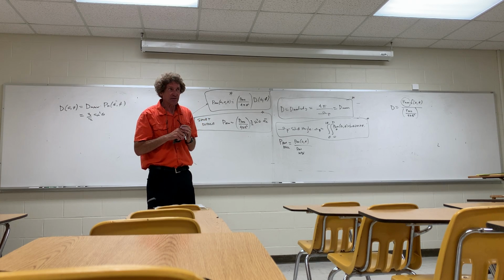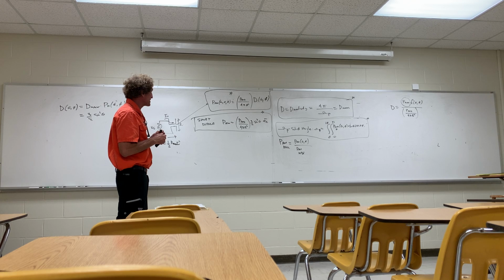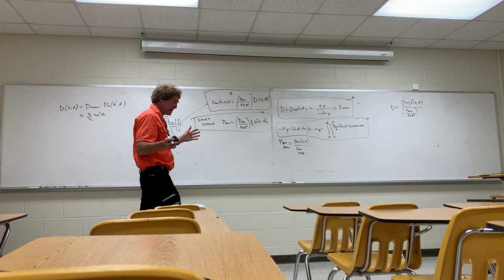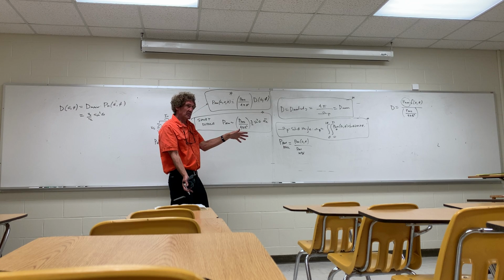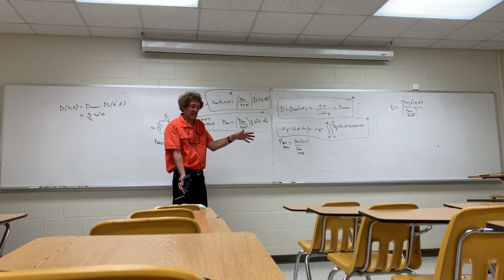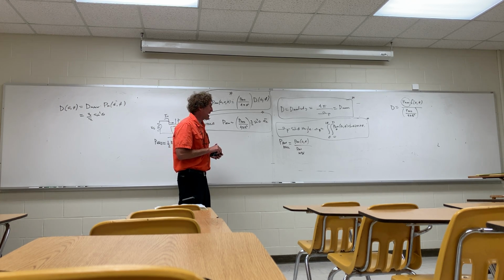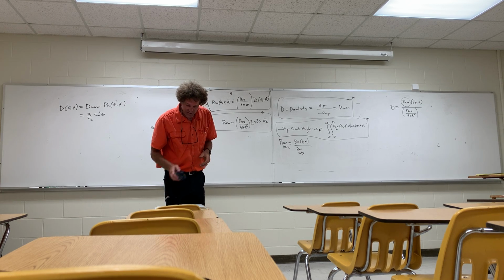I didn't have time to go through the development of directivity the way I like to, but this gives you the real essence of why directivity is so important. We're going to be talking about something called beam width, which is where most of the power radiates. You'll see these are logical things to ask. We'll take a look at power patterns and the power plots in cylindrical coordinates.